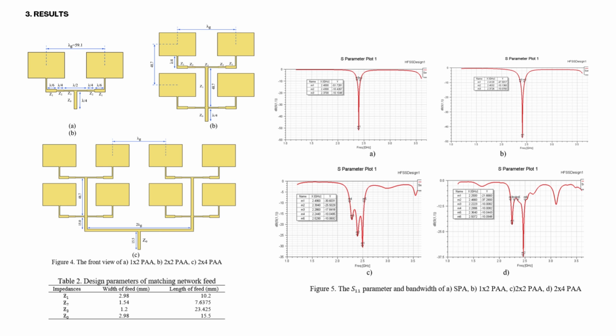In the realm of antenna engineering, the S11 value is a crucial metric as it quantifies how effectively the antenna converts incoming signal energy into radiated waves, and lower values of S11 denote superior impedance matching between the antenna and its transmission line, translating to reduced signal loss and enhanced overall performance.